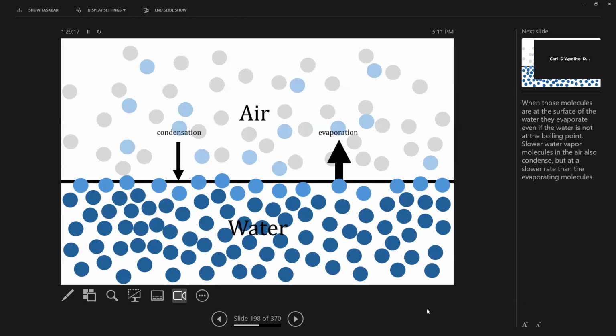When water evaporates, it takes a certain amount of energy to evaporate. So when you spray water into the air, the water evaporates, and that energy is essentially hidden. It becomes what's called latent energy, and it cools down the air because it took some of the energy to evaporate.